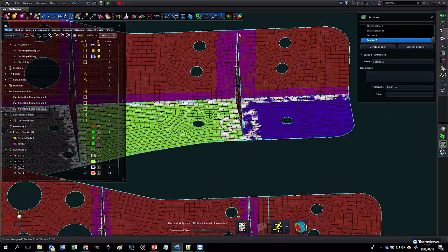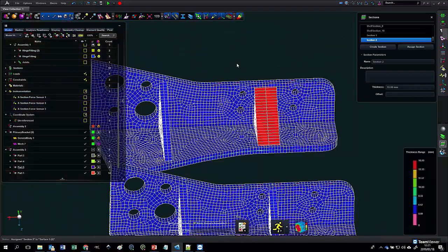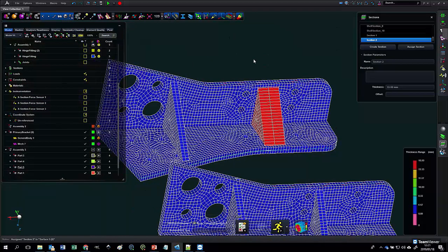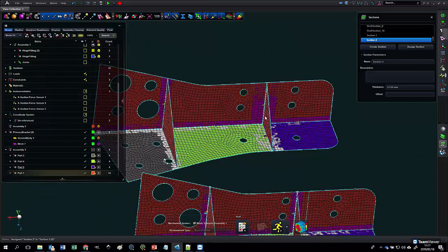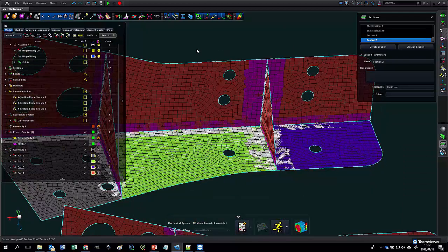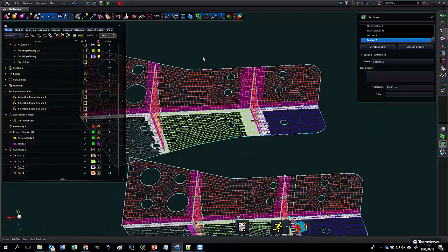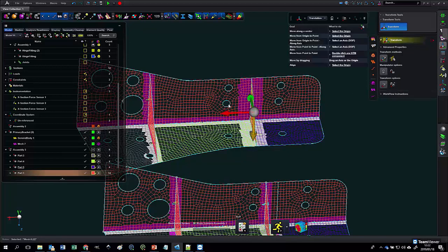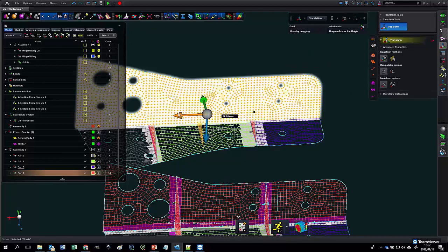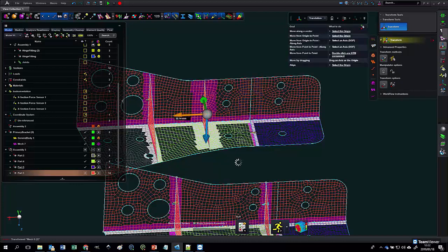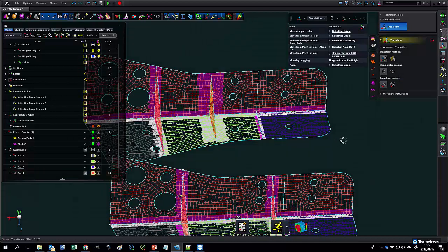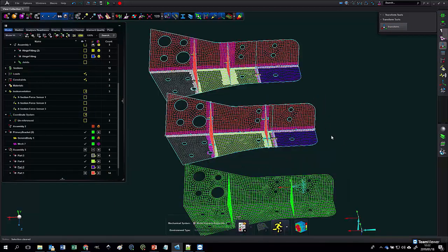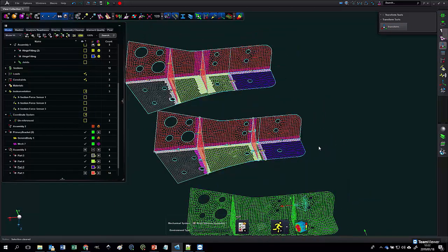And now you can actually see the footprint your glue has due to the thicker property of that body. You can see that body's got quite a thickness and it has a proper footprint, and it visualizes the elements that are in contact or glue contact. And this is all also generative, as everything is in Apex. So you can move this anywhere and your glue happens along with it, something that you cannot do with a stitched mesh that easily, at least.